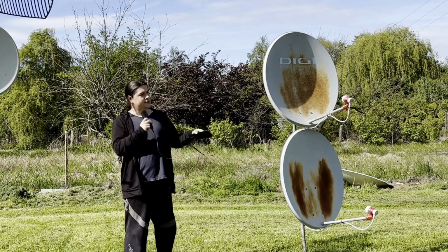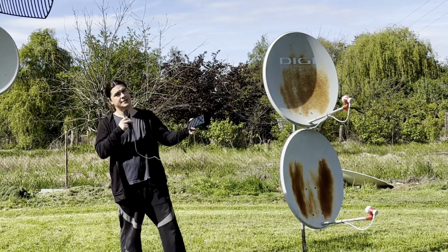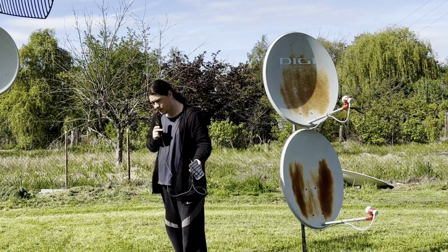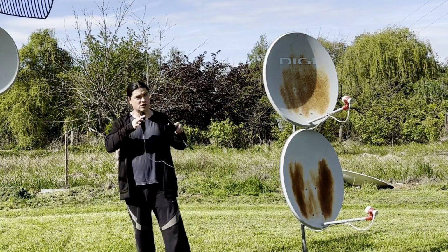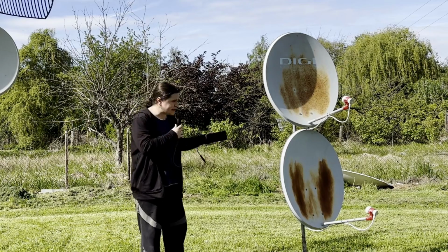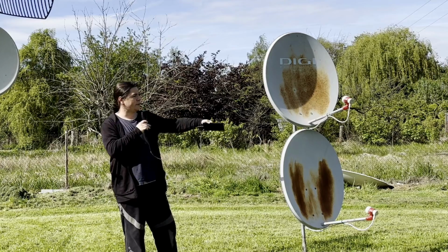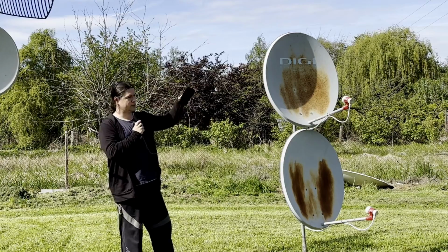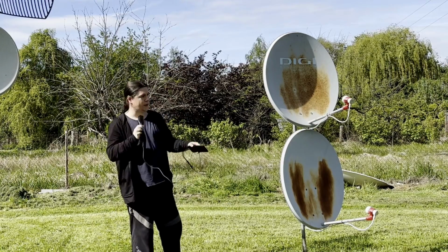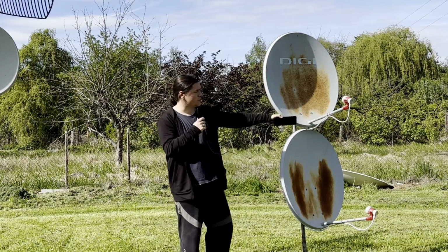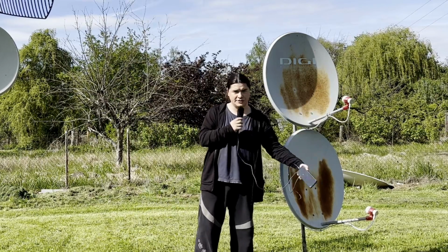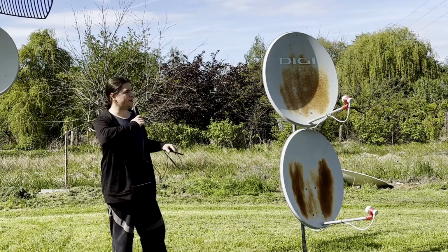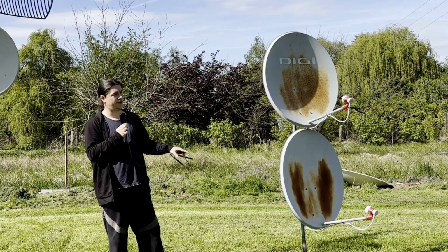Before we get to the SDR, we also need a way to power the LNB. Now some SDRs, again I have mentioned that in the Ku band video, some SDRs do actually have bias Ts, aka a way to inject 5 volts of direct current into the coaxial cable and power whatever active antenna you have connected on the far end. LNBs, they are going to need 12 volts to 18 volts. Aim for 12 volts. When you supply an LNB like this, 12 volts is going to be working in vertical polarization. Not only can you not do that with an SDR bias T, I also don't think it's safe to supply an LNB from a USB port.